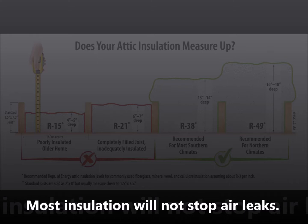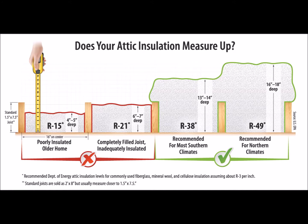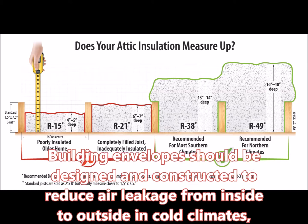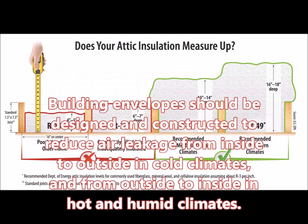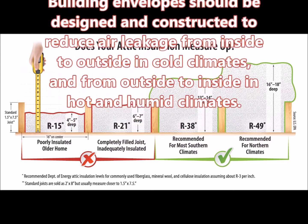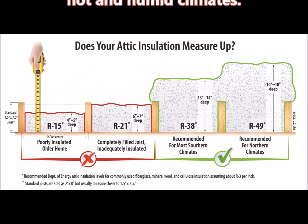Air leakage through building assemblies can move a large quantity of water vapor and is a major factor in many vapor-related moisture problems. Building envelopes should be designed and constructed to reduce air leakage from inside to outside in cold climates and from outside to inside in hot and humid climates. In order to achieve this objective, the big air leaks in the building's envelope must be sealed. Most insulation will not stop air leaks.